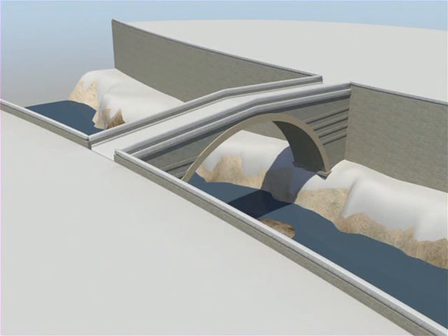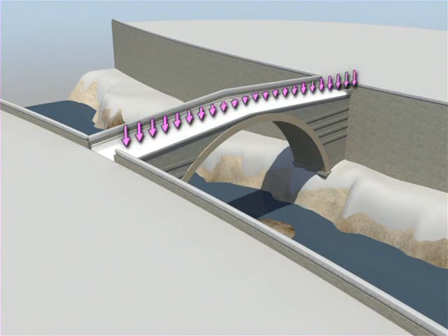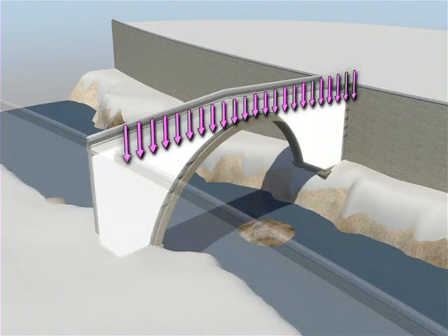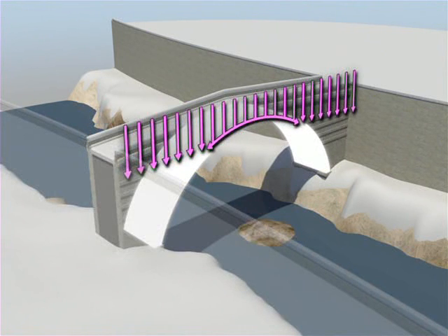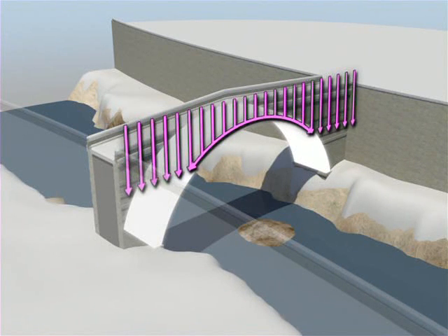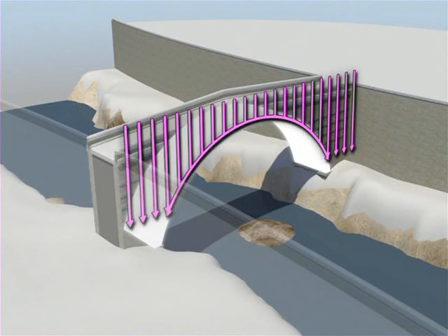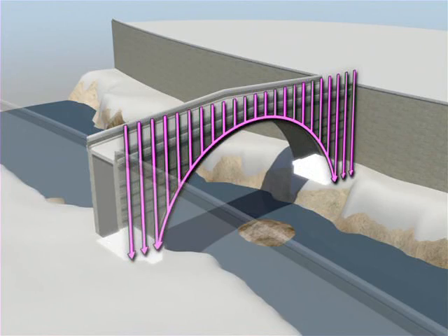The snow's weight is applied to the road surface and then transmitted down through that concrete fill to the main arch ring. And the arch ring then works exactly as we saw in Lecture 8, transmitting internal force in axial compression all the way down through the individual voussoirs out to the foundations.